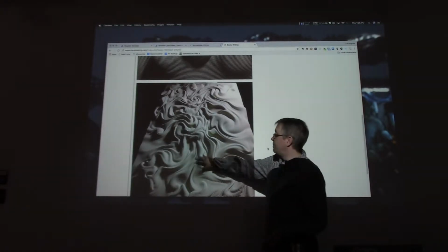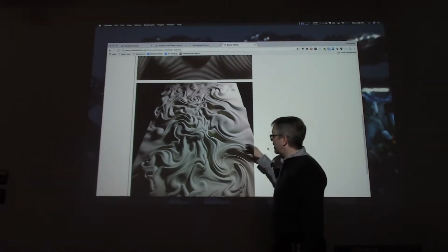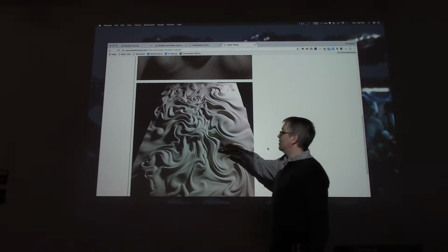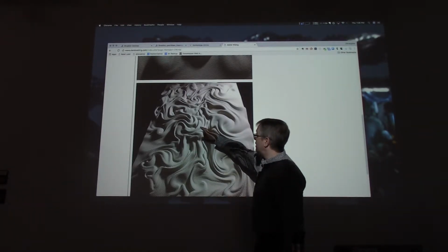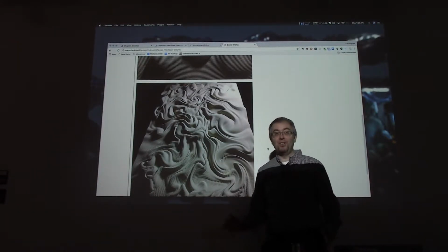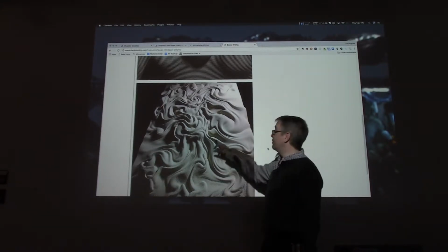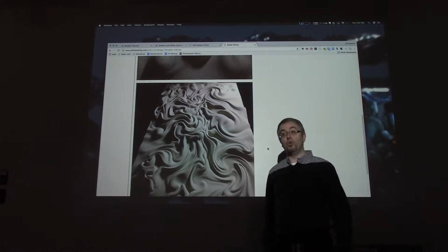The ball nose tip is going to leave that rounded circle, and then he's used the direction of those lines to enhance his idea to the point where he's actually done the algorithm so that you can see the CNC machine has done an outward spiral as its process of working, instead of the typical method of back and forth across or up and down or diagonal. He's actually reprogrammed it to do this gorgeous spiral to enhance the overall surface.